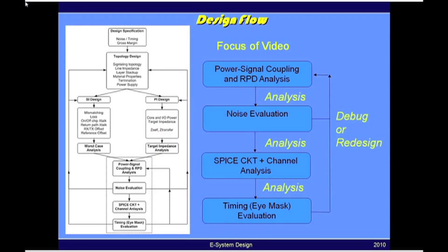So let me start this segment by proposing a design flow. If you look at the past, in terms of how we designed a system, we always categorized our networks into two fundamental kinds of networks. One to do with signal integrity, where we looked at all of the interconnects as transmission lines and relied on SPICE to do a lot of the simulations. And the parameters that we were interested in here were basically the reflections as well as the rise time at the output of the drivers.